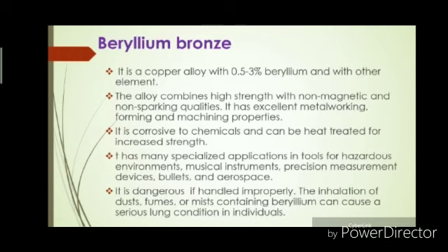Next one is the beryllium bronze. It is a copper alloy with 0.5 to 3% beryllium with other elements. This alloy combines high strength with a non-magnetic and non-sparking quality. Also, it has excellent metalworking, forming and machining properties.